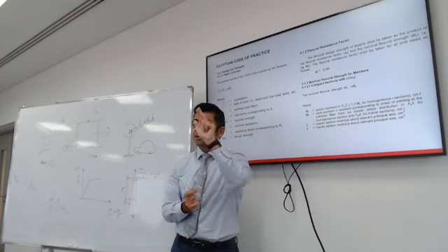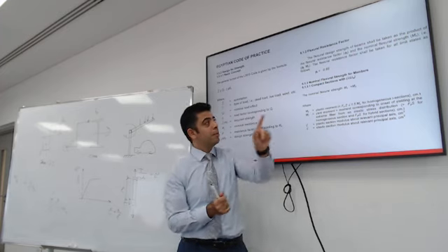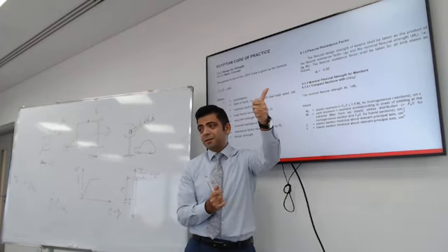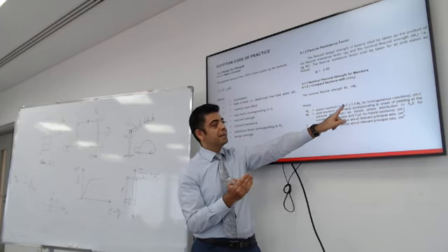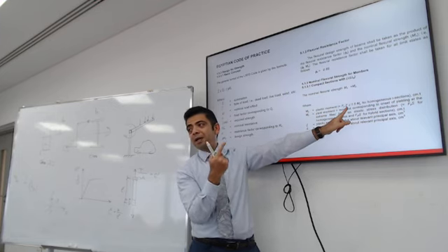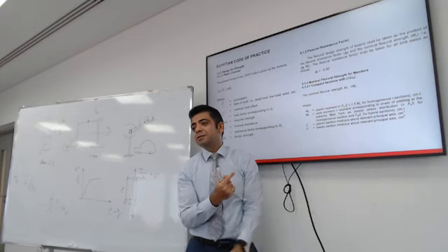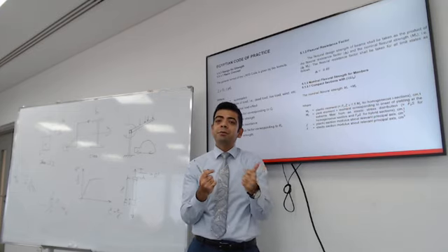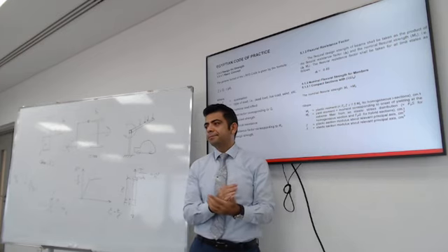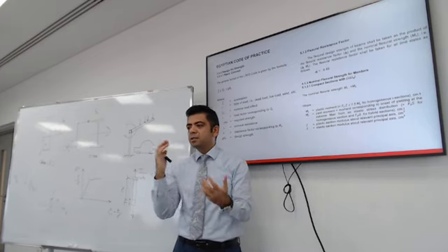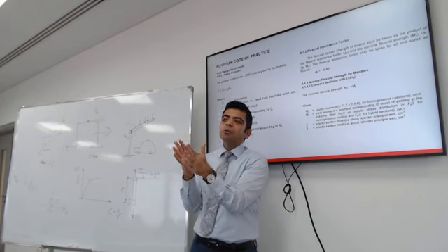It's the exact same three variables. F yield is F yield. Z is the section modulus. The Eurocode will call the section modulus W, the Egyptian code will call it Z. It's just whatever the text or document calls it.